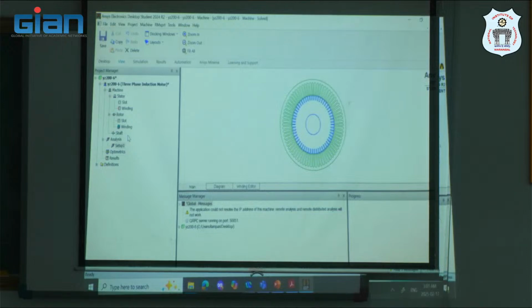That's the goal, because we want to do motor current signature analysis. So we want to run the motor excited from a supply. If the motor is loaded, it will draw current, and I am interested in that time domain current waveform. That is the goal. In order to carry out such a simulation, this software has what is known as a transient simulation tool.